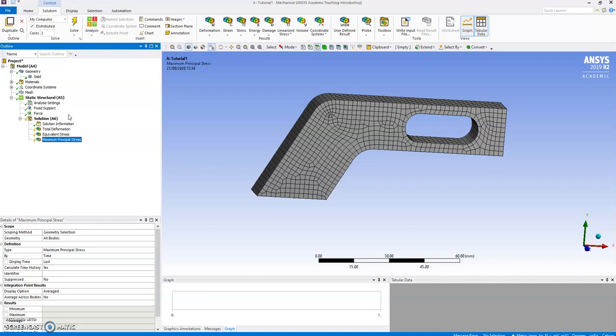There are others, of course, the maximum shear stress, and all these things. Of course, von Mises and maximum shear are only really meaningful for ductile material. Now I have got solid copper, and that is indeed very ductile. If you have got brittle materials, other failure criteria might be important, and you might want to apply something. And there is a lot of choice.